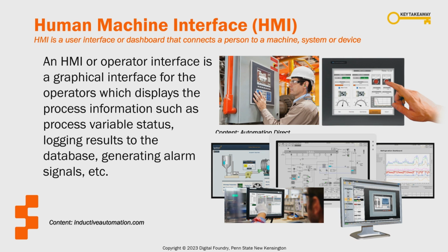In some machine control applications, multiple machine-to-machine protocols may be used, and often HMIs may be used for protocol conversion. This functionality can be used to exchange data such as status and set points among different controllers and other smart devices. Some HMIs can also send data to the cloud or enable remote access functionality through the internet, given proper username and password authentication.